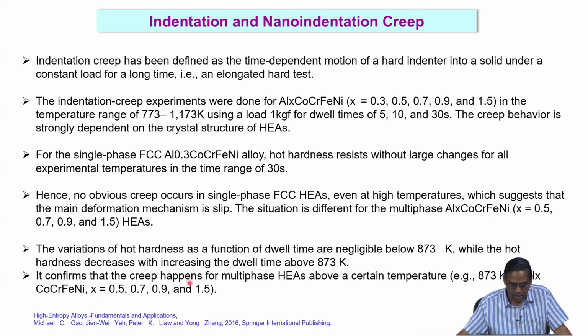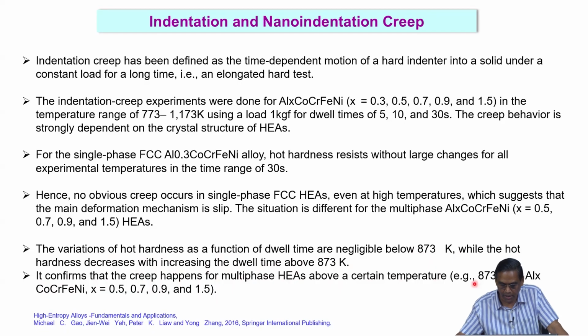But with increasing dwell time, there is some response. Okay. So it confirms that creep happens for the multi-phase high entropy alloys above a certain temperature. So not a single phase, but in multi-phase it has got an effect. So that is another piece of information.